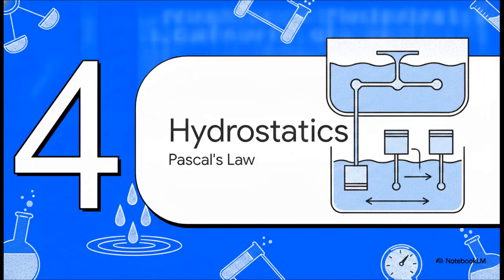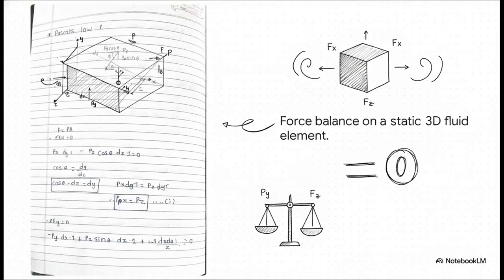Section 4. Pascal's law and hydrostatics. To prove these fluid pressure concepts, I want you to imagine mapping out the forces acting on a tiny, static 3D block of fluid. By setting the sum of those forces to 0 in the x, y, and z directions, because remember, the fluid is at rest, we can see exactly how pressure distributes. The math here proves that the pressure in the x direction equals the pressure in the z direction, and the pressure in the y direction also equals the pressure in the z direction.